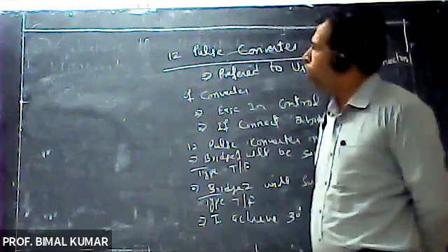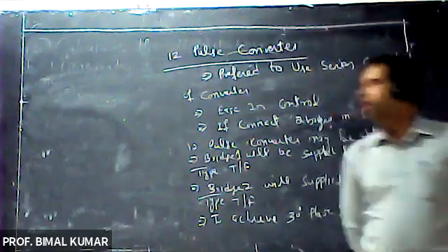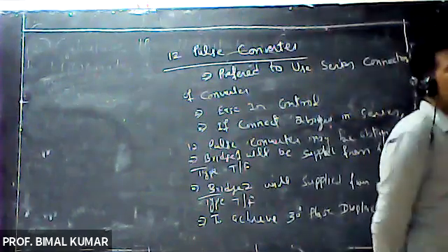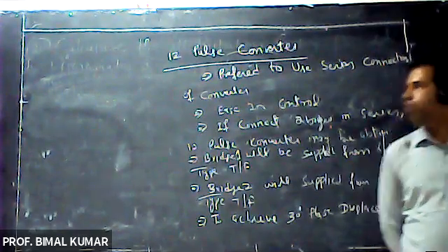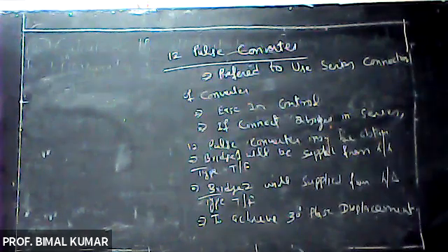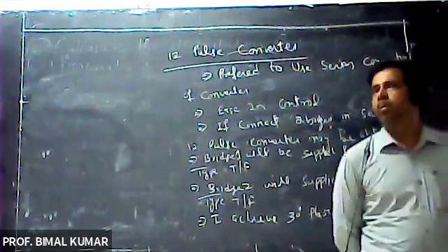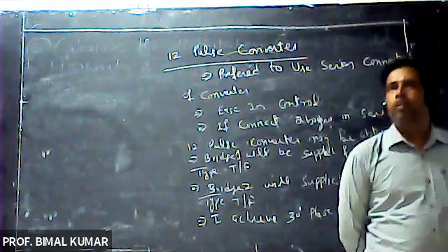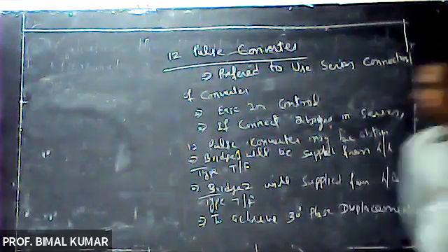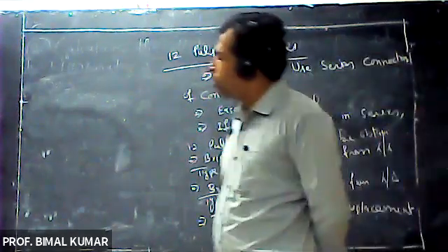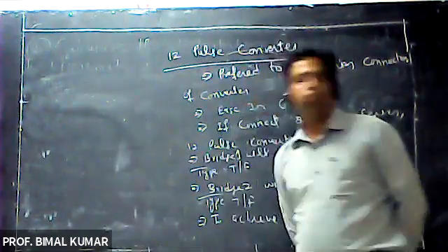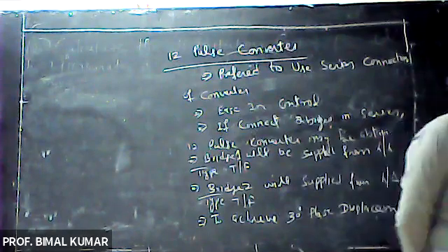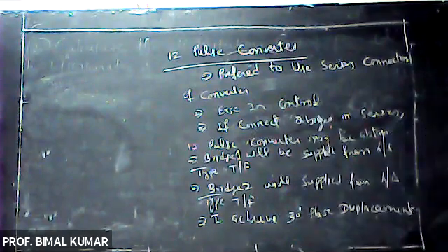Because interval of the pulses will become small, so we will get approximately constant DC without the help of filter. That's why we will prefer to use 12 pulse converter over 6 pulse converter.